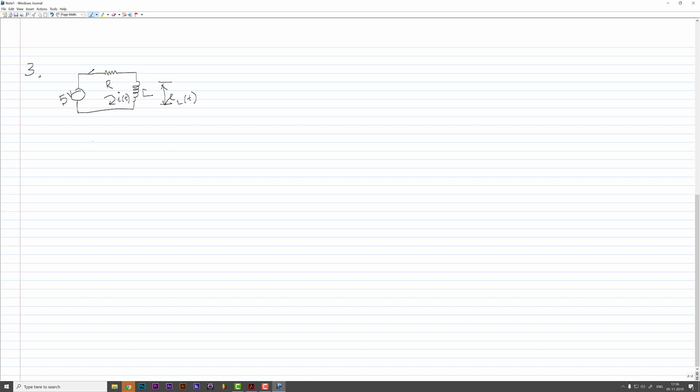So you can write the different equations and form the differential equation and then go ahead as usual. The first equation is EL of t equal to the voltage across any inductance, which is L di of t by dt. Am I right? Then in Laplace transformation this can be transformed as EL of s equal to s L I of s.